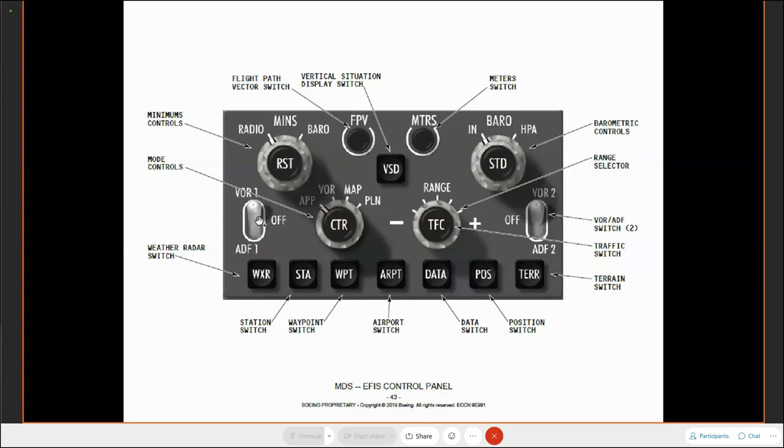Down here is to do with indications for the nav displays, VOR or ADF. ADF is an option on the aircraft. ADF is an option in many countries now. However, if your aircraft flies in EASA airspace, and I believe in Russian airspace as well, it has to have an ADF fitted. I'm sure there are other regions around the world that still require ADF as mandatory. But certainly in my part of the world, EASA for the time being, until a few weeks' time. But I'm sure the CAA will go down the same lines as the EASA. I can't see things changing too much on those things.